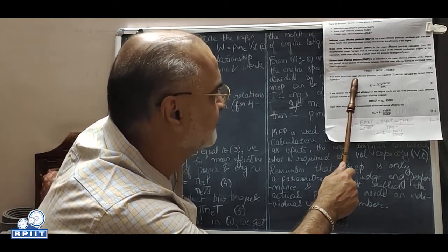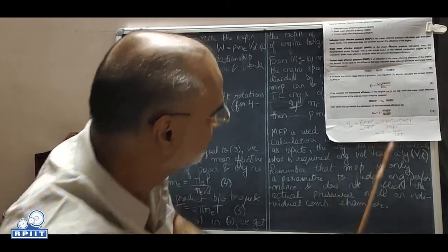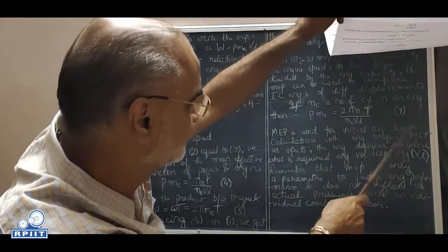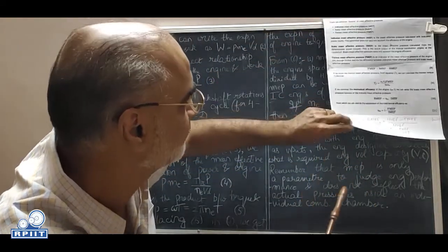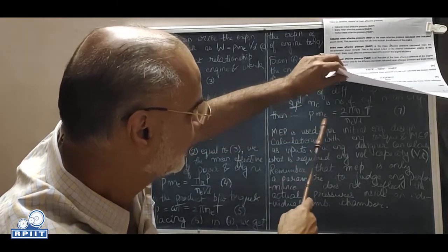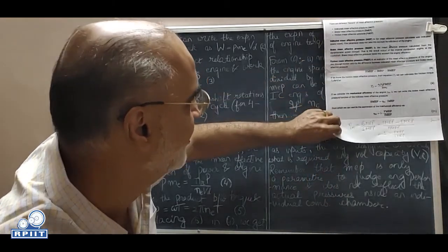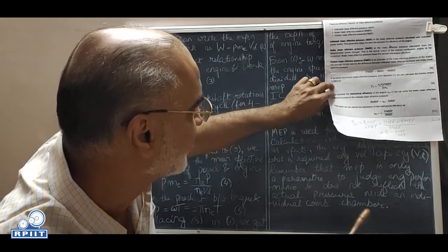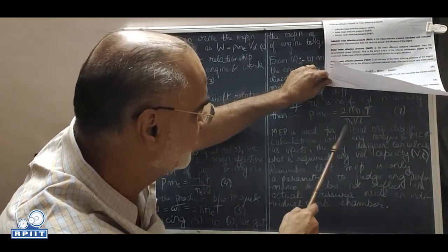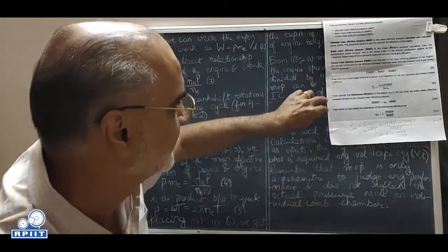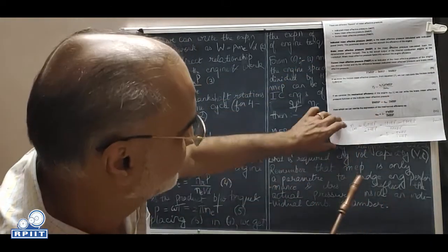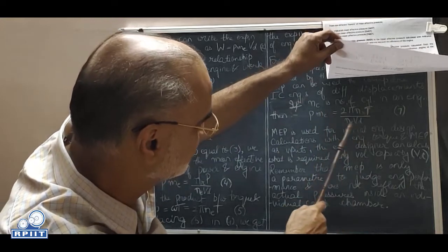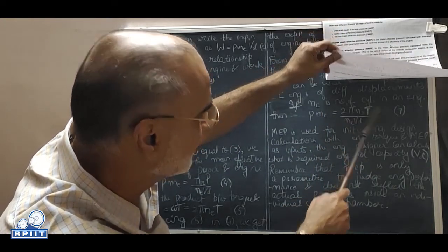If we know the frictional mean effective pressure from equation 7, we can calculate the frictional torque TF from it, by multiplying by the displacement and dividing by 2 pi nR. This gives the frictional torque.